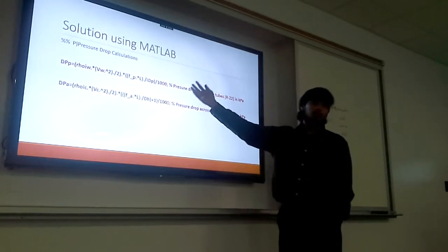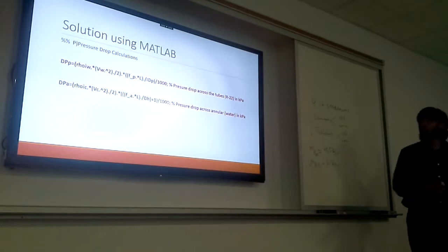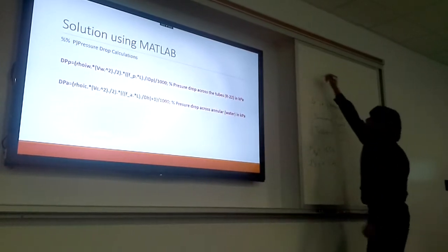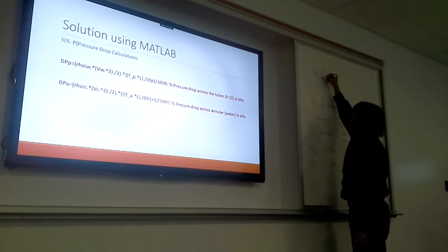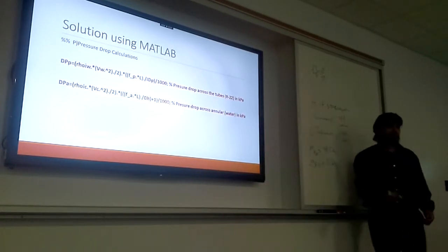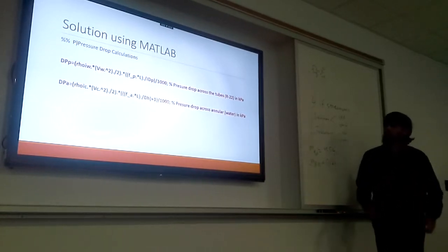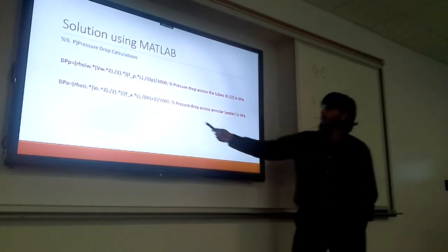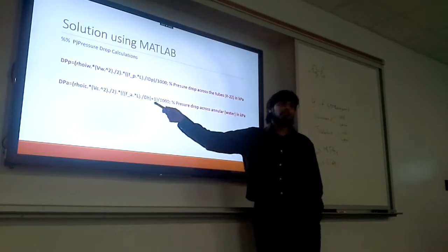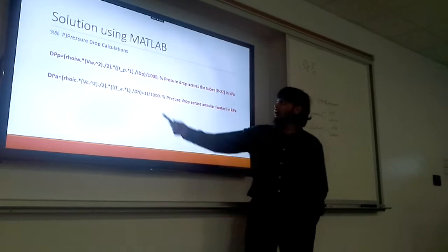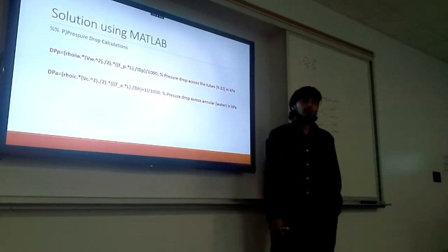And the pressure drop, you guys know the equation, you're already familiar with it, right? The whole f L over D, V squared over 2g. Right, you've seen it several times. So you just use the same concept over here as well. There is a small difference for the annulus one, or basically the non-circular one. Just make sure you account for that. And then I divide by 1,000 here because I want it in terms of kilopascals. Okay.